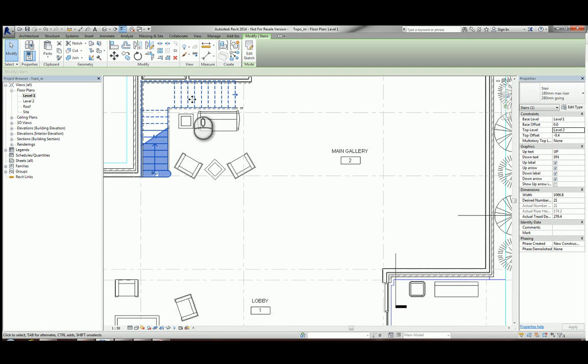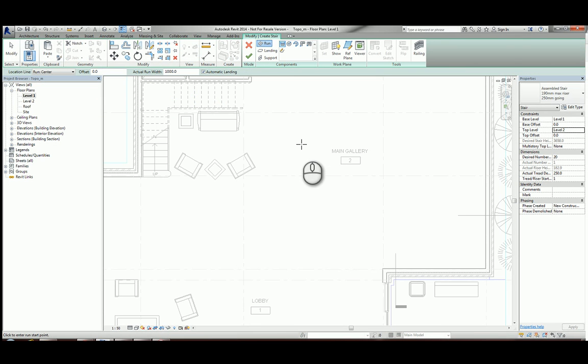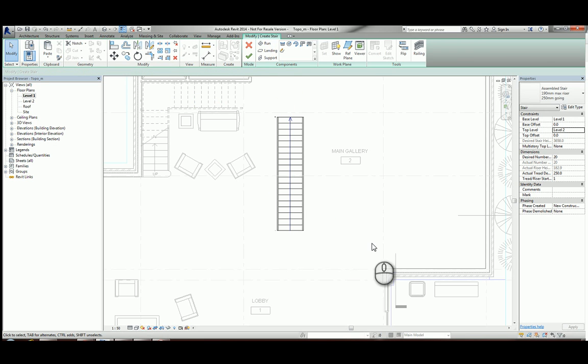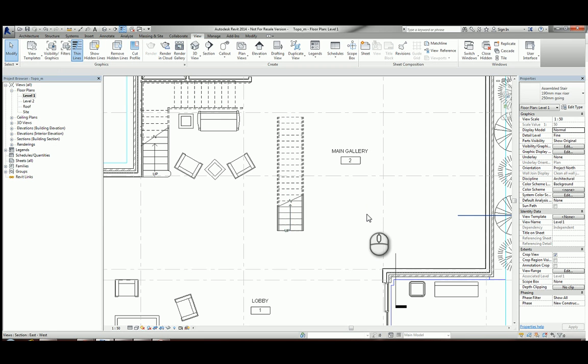Now, one of the things with Revit is if you create similar with the stairs, even if the stair was drawn stair by sketch, it will actually do it stair by component for the new style. And all I'm simply going to do is use exactly the same style, but draw a straight run like so. Once I've finished my stair, there we go, my stair. It will look very, very similar to that, but it was created stair by component.